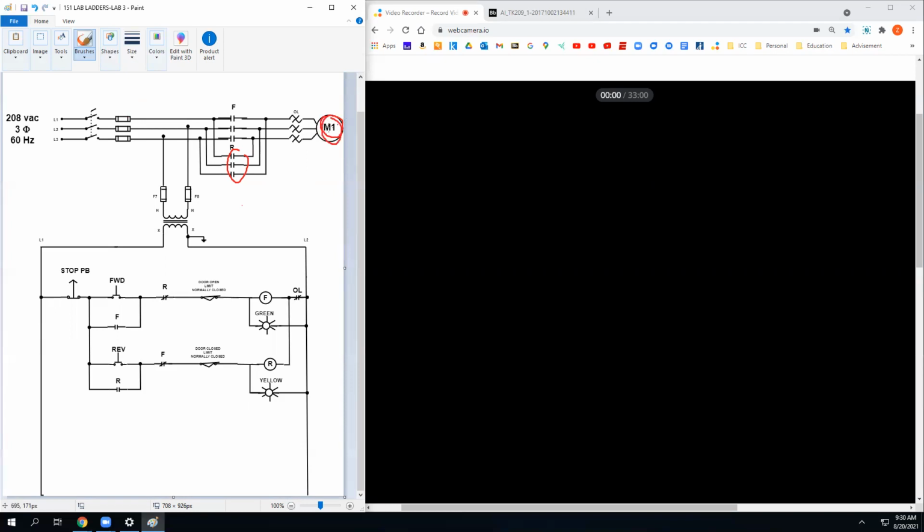No, you could start there, but you'd be wasting your time. The output would be this reverse thing. But I'm telling you, okay, that's not pulling in and the yellow light is not turning on. So we got no output there. We got no output there. Output back means you start here and you work your way back. So what's the first thing that you're going to check voltage on?